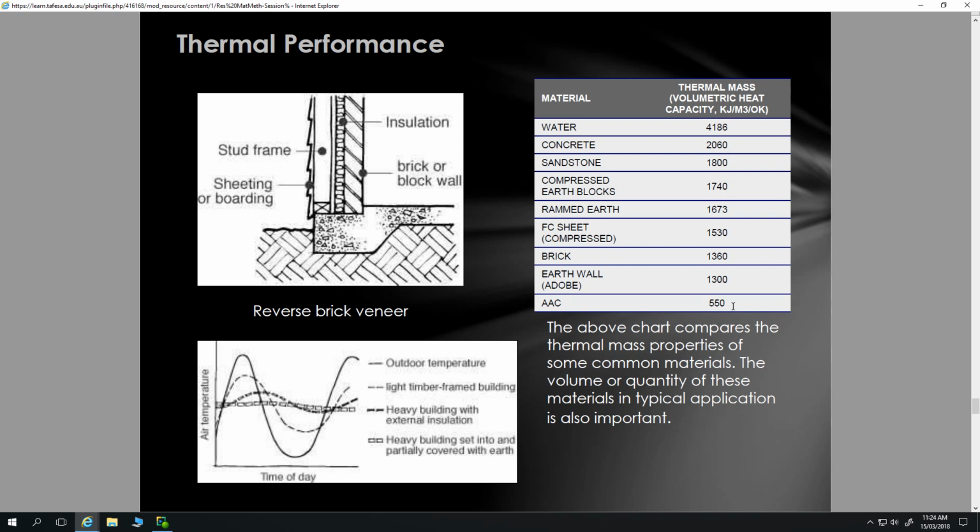So yeah, that's the thing of, I guess, essentially unpacking the marketing around it. So thermal properties, yes. What aerated concrete is good in is it has a higher R value, and I can't think of the typical R values for the thicknesses of your sheet, but it provides insulation. So that table up there is dealing only with thermal mass, and so it tells you how it works as a heat store, but Hebel also works in insulation as well, so stopping the passage of heat through it.